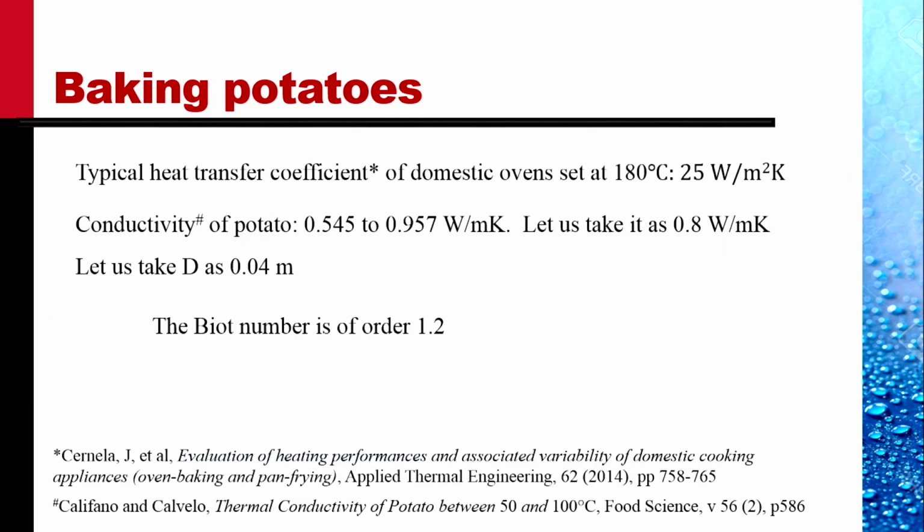Typical heat transfer coefficients of domestic ovens set at 180 degrees centigrade is of the order of 25 watt per meter square K. The conductivity of potato is between 0.545 and 0.957 depending upon the water content within the potato, depending upon how old the potato is, how long it has been stored.